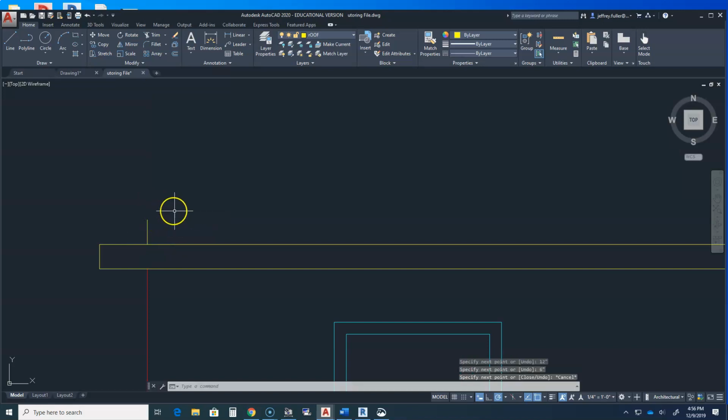The end point of the 6-inch vertical line represents a point for which the slope should pass. Press the Enter button to get the line tool to reactivate. Place the start point at the top left corner of the fascia like you did before, and draw the line to the end point of the 6-inch line. Do not click to place the next point, just lock onto the end point. Jot down on a piece of paper the angle of the slope, which should be 27 degrees. All of your slopes should be 27 degrees.